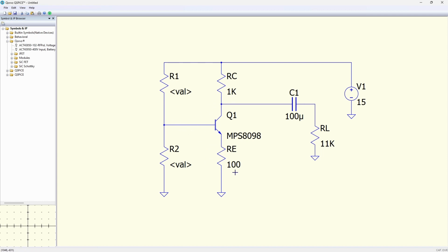So if you don't have a resistor here at all, you can imagine this. If this were 0 ohms, or we just took it out and shorted to ground, then VBE would be connected directly to this node. And VBE is a diode. So whenever we increase our voltage on the left, it would increase from 0 to about 0.7 volts with no problems. But then it would clamp there. The diode would hold you at that voltage.